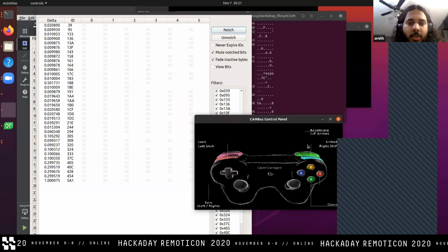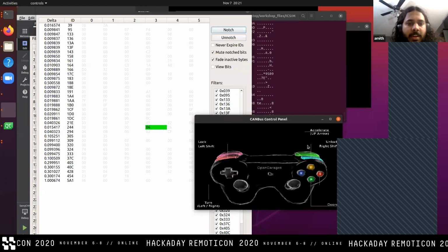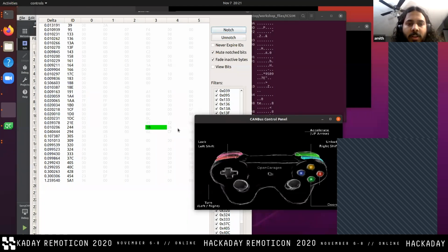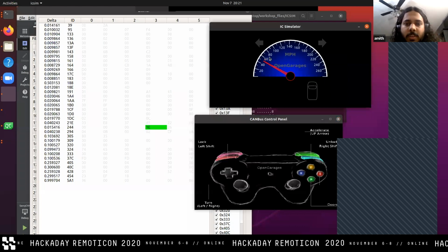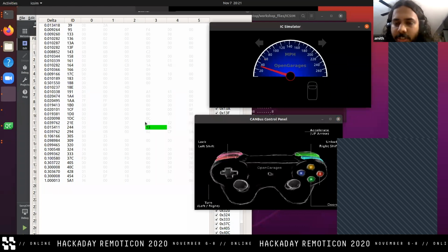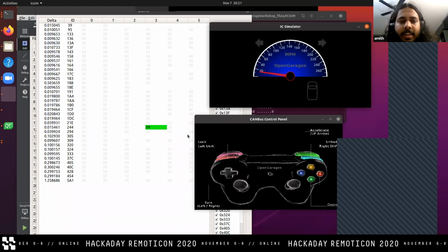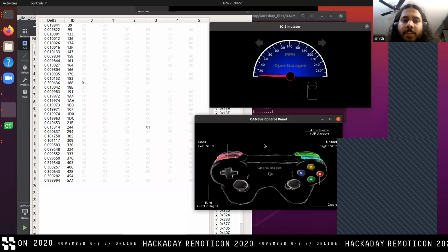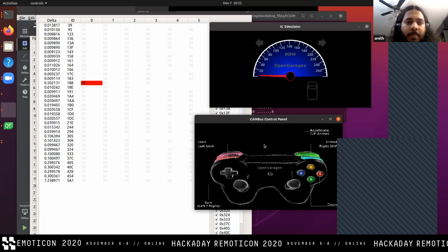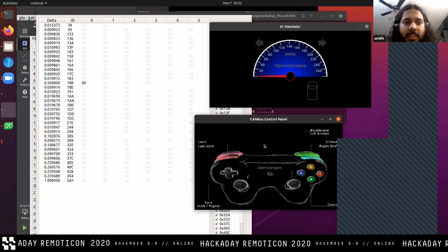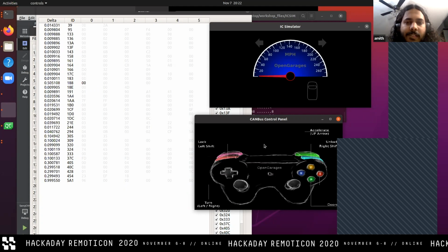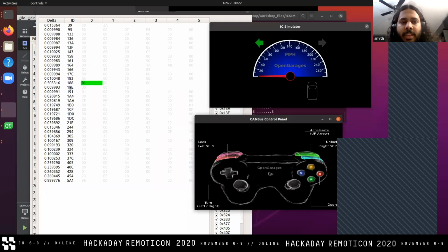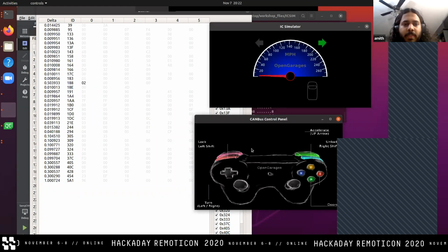Then I'm going to do the same acceleration command. Okay, there. Right now I can see that it's 244, the CAN ID the acceleration command is tied to. It's a lot easier to see with SavvyCAN, but obviously I can't get everyone to install that program. I'm going to do the same thing with the signals, and you can see that 188 is the CAN ID for those signals.